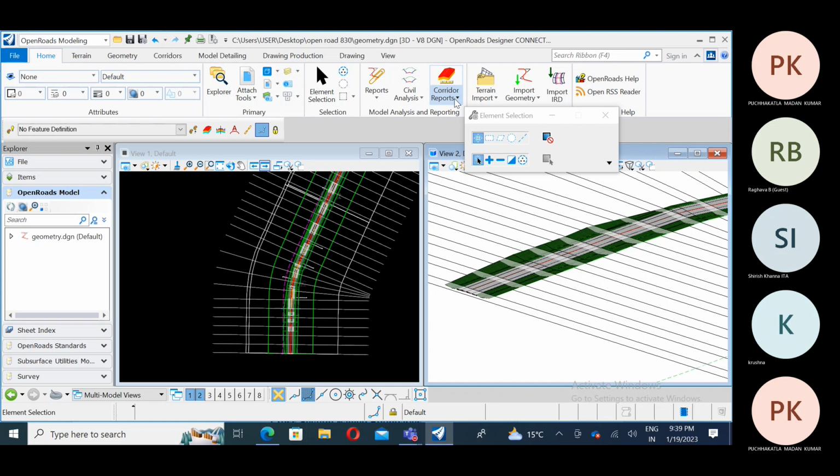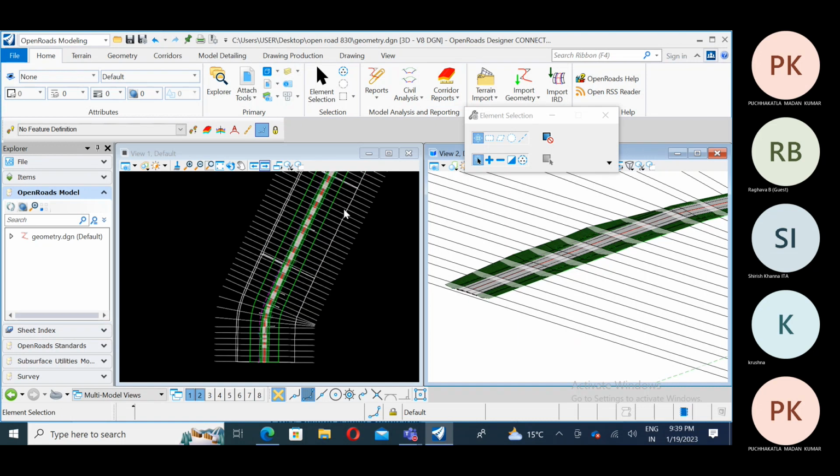Then the named boundary we learned today. So try to do this first, then we go for the end area, fill and area volume report, and then that diagram, and then the last topic we have is drawing production, so that we get the detailed drawing of our road, the actual profile, plan, and cross sections.